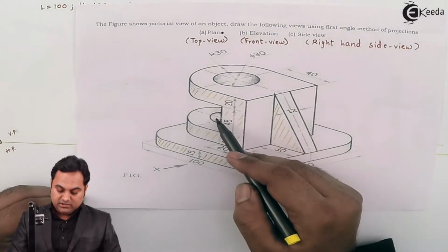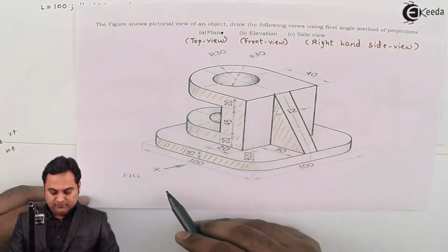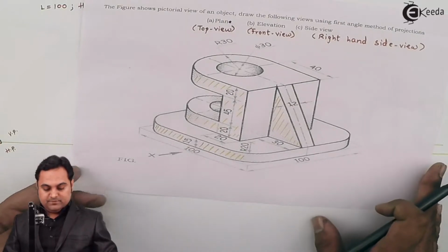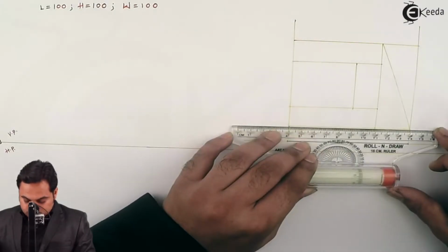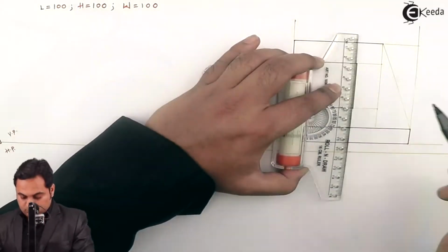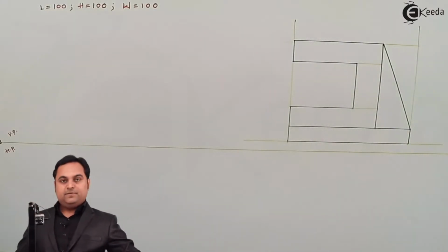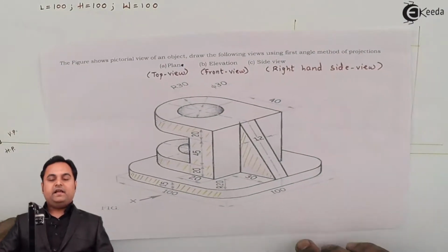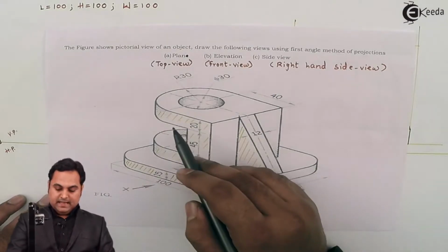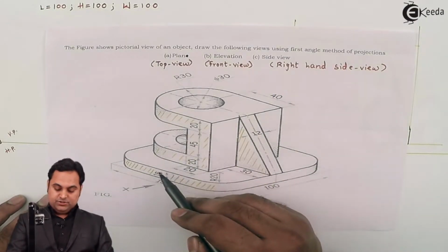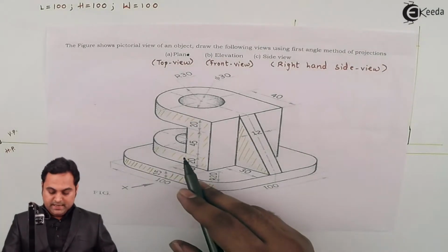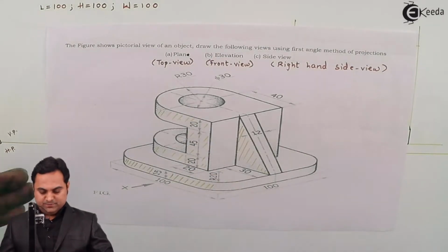Like these two circles won't be visible from the front view, so they have to be hidden. First I'll draw the visible portion dark. So this is the visible portion, and in the diagram if we can see, this plate of 15 mm height and these two plates are not on the same plane, means this plate is forward and these two plates are backwards, behind.